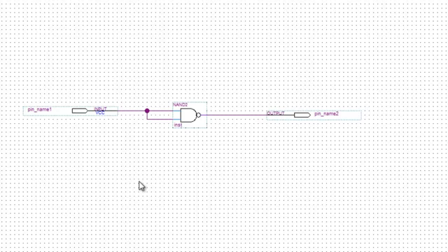The other thing that I'm going to want you to make sure that you do is not use the default pin names. Please select pin names that make sense. So there's two ways that you can get at these. One is to double click right where the name is. It will turn blue, and then all you basically just type. So I'm just going to type a capital A because I want that to be A, and then I'm just going to click outside of that input and the name will be changed.